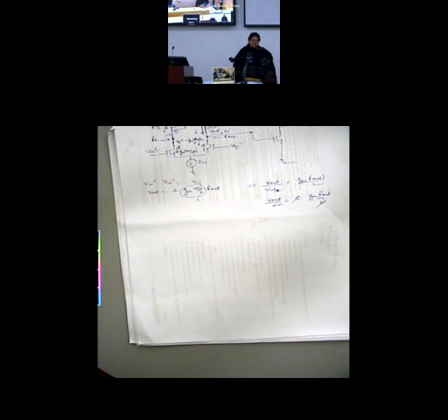Now you do not have matched arms. I can have matching between transistors, but the differential amplifier topology is no longer matched. So again there is a problem. You may have differential operation not happening because symmetry is required for difference operation. So if you have an unmatched or unsymmetrical differential load, what are the conditions in which you will get difference operation? You can still get a differential gain.